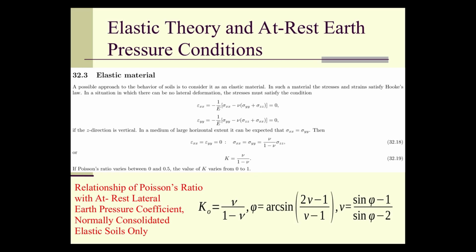Soils, as I've mentioned, are kind of an intermediate material between true engineering solids and fluids. Some soils, like very soft clays, may act as fluids, but to get down to brass tacks, in many cases we use nu equal to 0.5 for a lot of simplification of Boussinesq equations and whatnot.